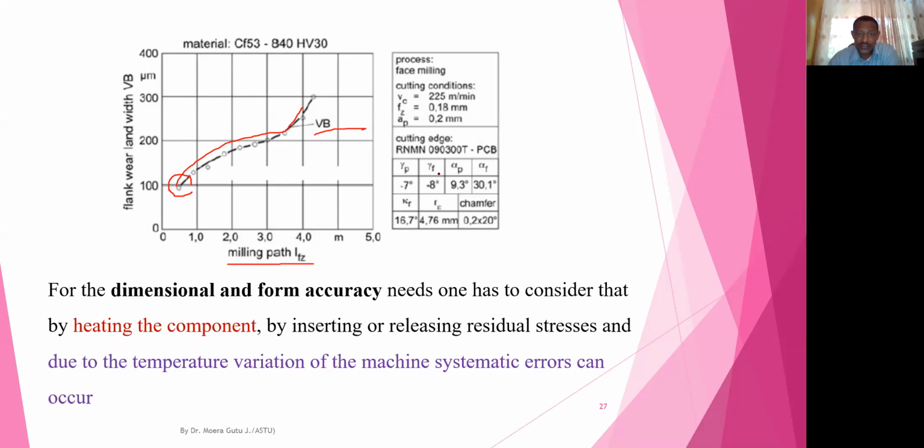Here you will see these are the values only when this research is conducted: the relief angles, the rake angles, and the clearance angles range are here. When you do research, you also have to mention what relief angle, what cutting clearance angle and rake angle you have used. You have to mention also the required surface finish you obtain, the VC, the cutting velocity.